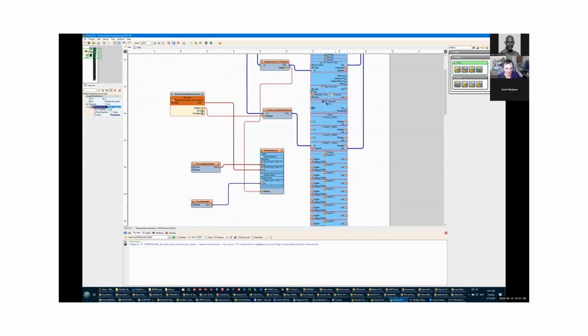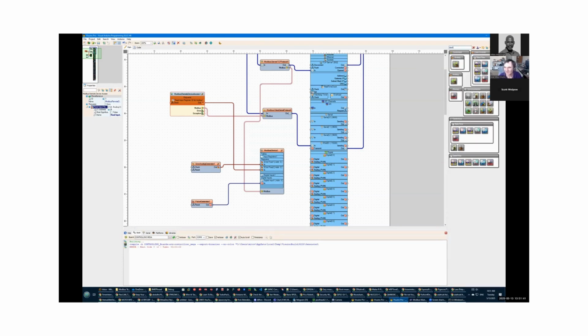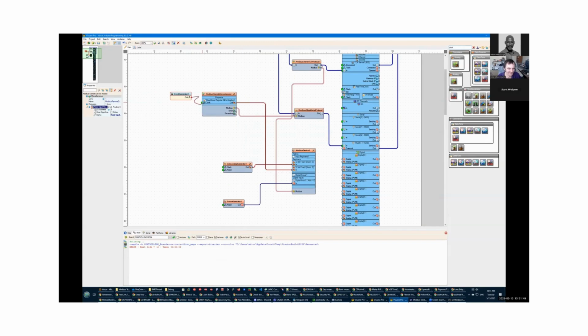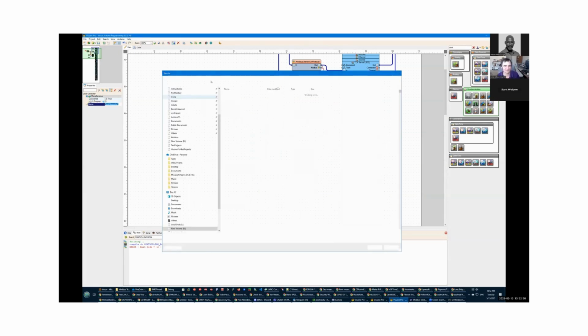In theory. No, we're not cool. We need to clock it. Yeah, I forgot that. We need to read that with certain frequency because Modbus is a slave type of protocol. So I have to specify how often I want to read this device. And I can read it, let's say, 2 times a second. Okay, don't want to overload it.